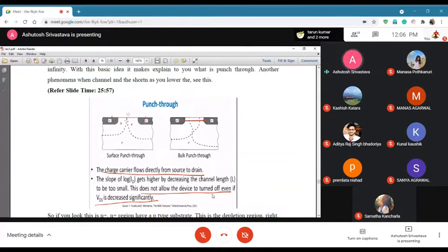So when you reduce the channel length, guided by the postulate given by Gordon Moore, and coming from using either constant voltage or constant field scaling or a mixed bag of the two, you're coming to a stage where there is an interference, or a meeting point, of the depletion region that is due to the N plus P source region and N plus P drain region.